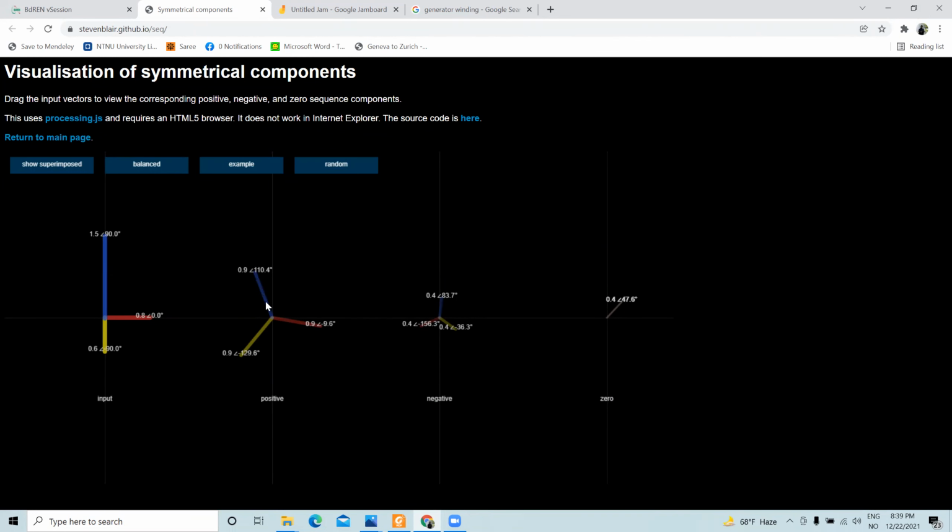Here you can see the blue line, and after that the yellow line and then the red line. Here it's blue and then the red. If this sequence is positive, this sequence is the opposite of it, so you have to consider from this part. So this is a negative sequence. If this is positive, then if you go clockwise, it becomes negative.